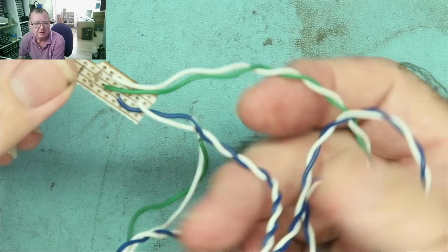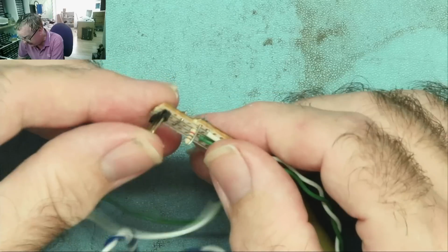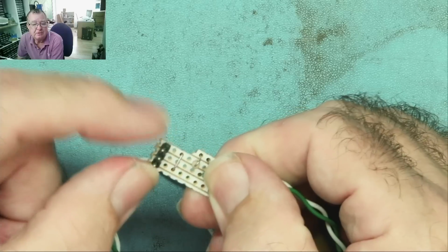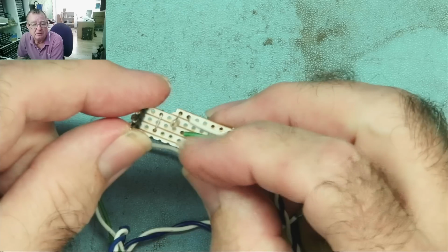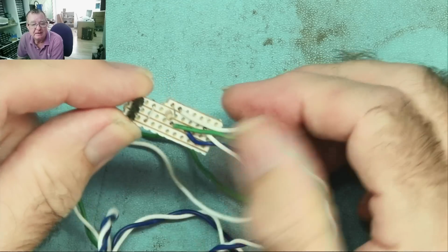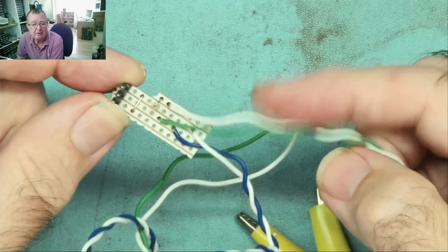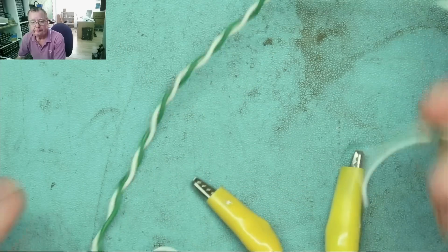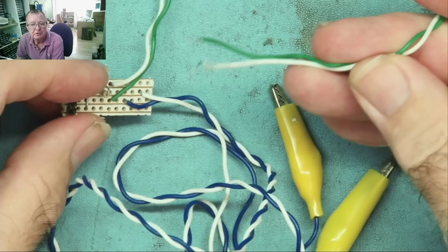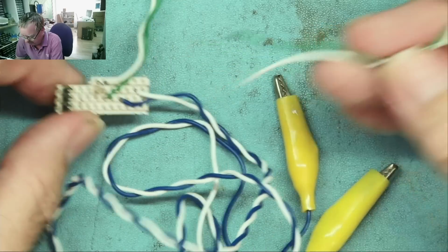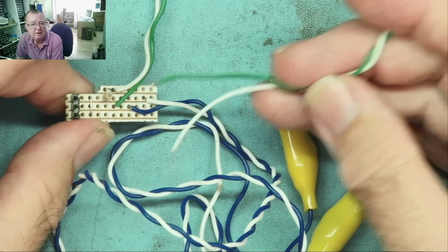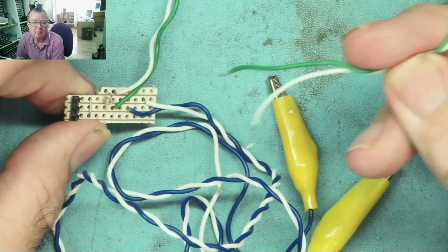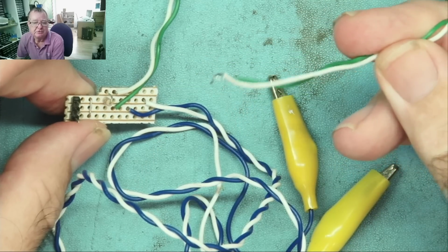And then we have 2 sets of wires. If you look at it, the little wire link connects from one end of the pins to the other end, so from there to there, and the 1K resistor goes from the middle pin to this track. So this white wire here coming in, this is the supply voltage, and I can connect this to my bench power supply. The supply voltage doesn't really matter, 5 volts, 9 volts, whatever you fancy, because the TL431, if it's working, will regulate the voltage. So we connect to the bench power supply with the white to the positive.